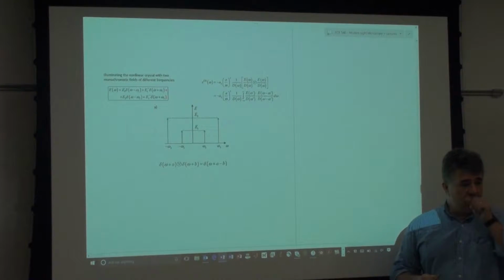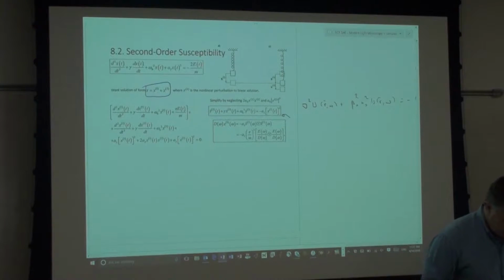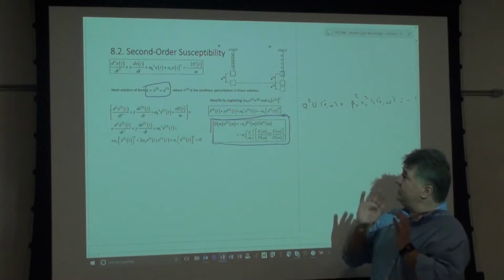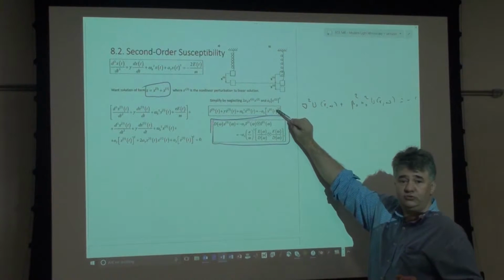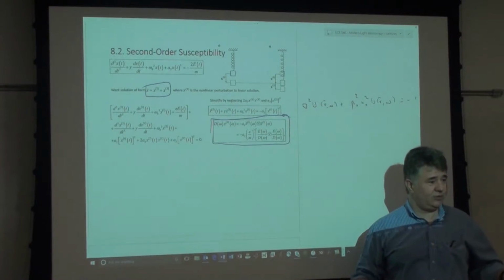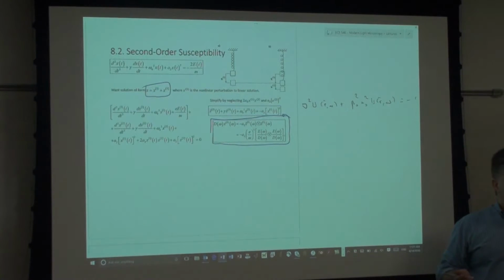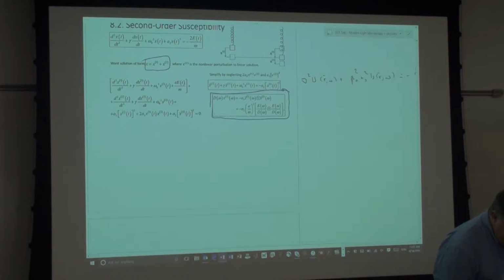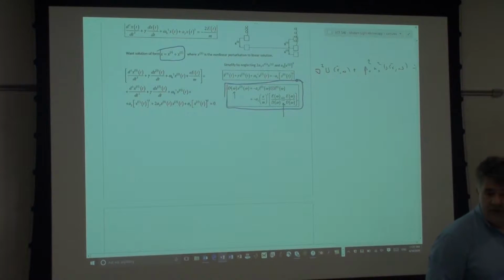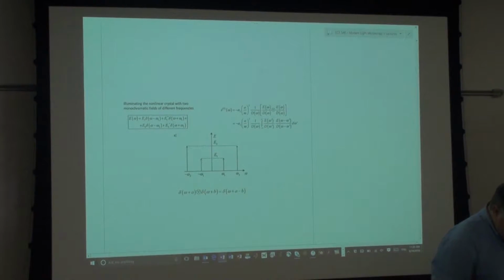Now, let's suppose, are you with me, guys? It's a lot of equations in here, I'm aware, but I'm trying to explain more or less what it means. So for example, we're talking about second order nonlinearity, the fact that your driving term has x squared in it. You would expect right away that there will be some double frequencies in there, right? We can anticipate that. So I'm trying to use our procedure here. So we went to the frequency domain. This x1 of t squared, Fourier transform of that gives you a convolution with itself. Yeah?